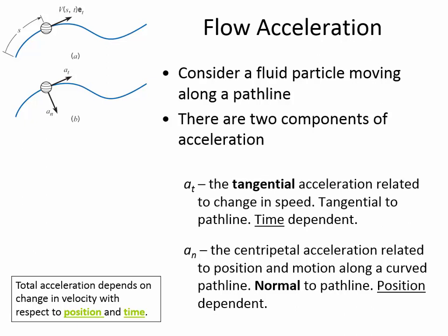In the case of the circular motion, even when it achieves a constant speed, it's rotating at the same rate, they're still feeling an acceleration. And so in that case, nothing's changing with respect to time. So conditions are steady in the first video that we saw. But what's changing there is the direction of the velocity vector. Because remember, a velocity has two components. It's got magnitude and it's got direction. And so in the circular motion, the direction of velocity is changing, and so an acceleration is required to do that.